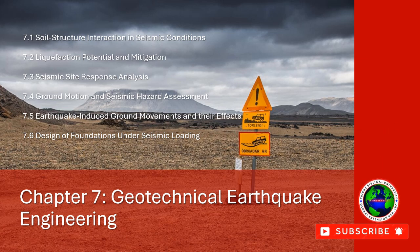5. Liquefaction Potential Index (LPI). The Liquefaction Potential Index (LPI) is a composite index used to quantify liquefaction susceptibility based on factors such as SPT blow counts, depth, and soil type. It is often used for rapid site assessments and hazard analysis.